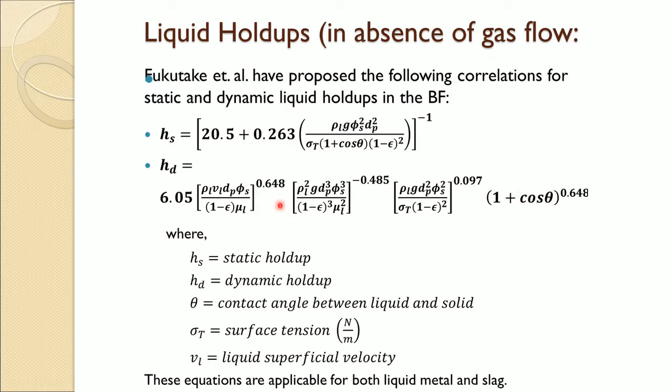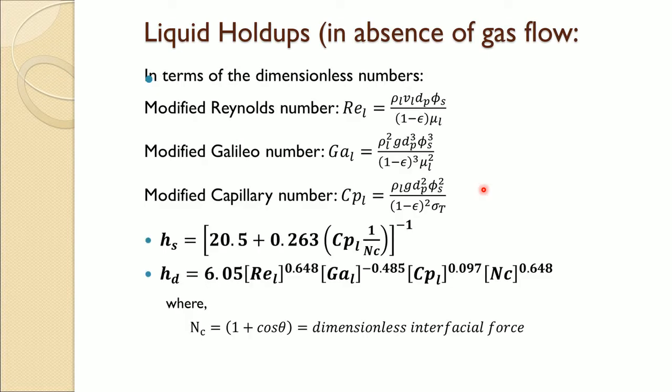So, if you represent it in these quite well known non dimensional numbers, then you can write the equation in those terms. Static hold up is a function of the capillary number and interfacial force number, and the inverse of that, and the dynamic hold up is a function of the Reynolds number, capillary number, interfacial force number, and inversely the Galileo number.